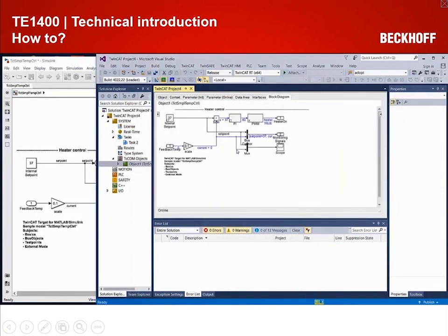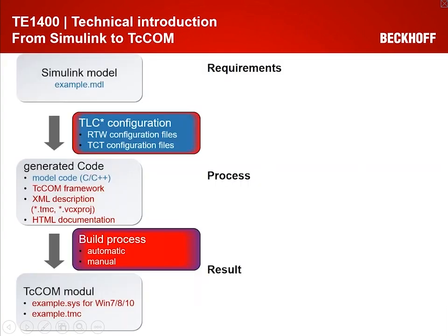No, of course not. So this is the workflow in general. Start with Simulink, click build, load the build TCCOM object in TwinCAT, and just use it. And to give you an impression on what's happening behind the scenes, I want to go over to this slide from Simulink to TCCOM.